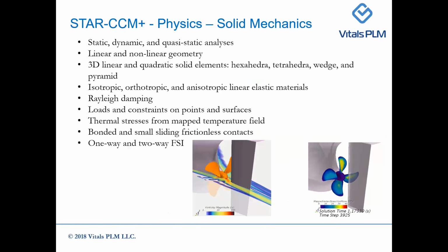STAR-CCM+ provides an integral finite element solver for the solution of solid mechanics, fluid structure interaction, and thermal stress problems. Here we can solve static, dynamic, and quasi-static analysis, linear and non-linear geometries, 3D linear and quadratic solid elements like hexahedra, tetrahedra, wedge, and pyramid-shaped cell elements, isotropic, orthotropic, and anisotropic elastic materials, Rayleigh damping, loads and constraints on points and surfaces, thermal stress from mapped temperature field, bonded and small sliding frictionless contacts, and one-way and two-way FSI.